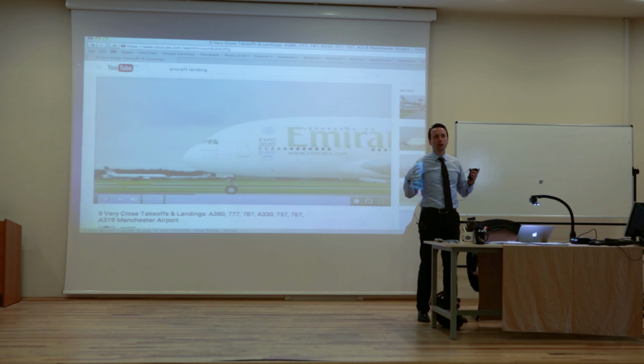Okay? There were cases where I've seen people trying to measure that rotation from V infinity, but that's not very reliable. It's not useful. There might be wind coming from this side, no wind on the other side, and you might be thinking you're turning and all this stuff. What you're really interested in is the pure V infinity that this fuselage will see.